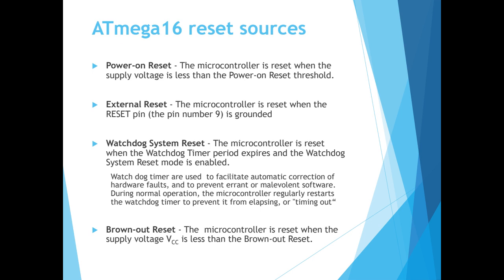Reset is typically generated by a hardware signal from external sources. For example, you might find a reset button on the development board. Most microcontroller devices have an input pin for reset, and if a low level is on the reset pin for longer than the minimum pulse length, it will generate a reset.